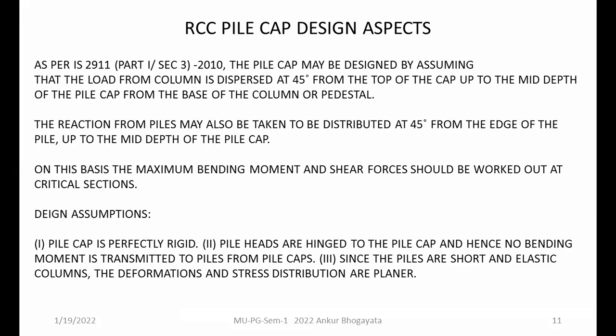So once you introduce bending inside the piles itself, I'm talking about pile itself, the diameter will unnecessarily get increased, and the behavior will not be predictable, because once it goes into the flexure, it starts behaving like a slender column also, because the length of the pile is tremendous always. And that is why it is called deep foundation. So here we have to assume that piles are just getting connected and placed in shape and in place by means of pile caps itself.